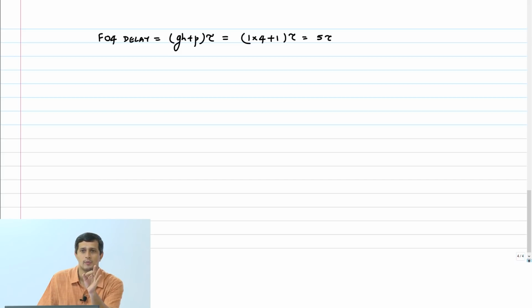If you are in 180 nanometer, half of that is 90, 1/3 is 60. So the FO4 delay will typically be between 60 to 90 picoseconds. Okay, and then you can calculate what the inverter delay is, which is just 1/5 of the FO4 delay.